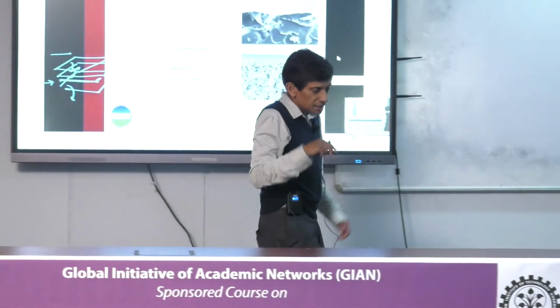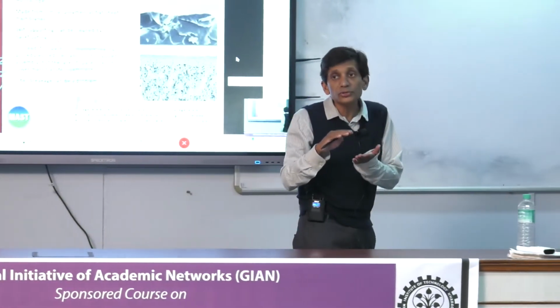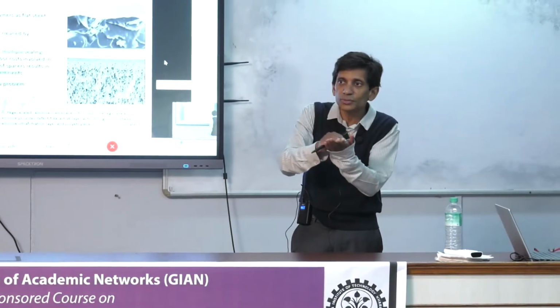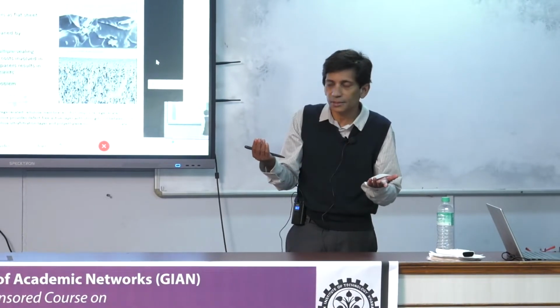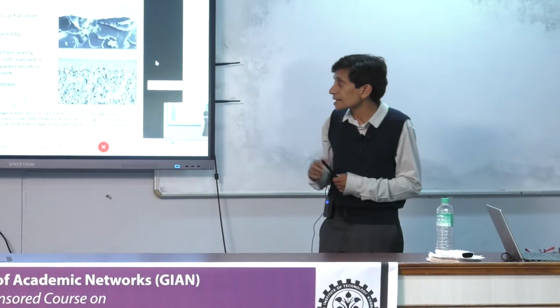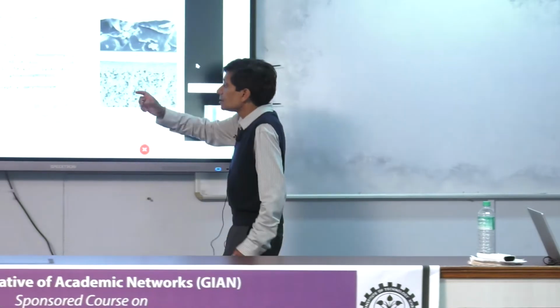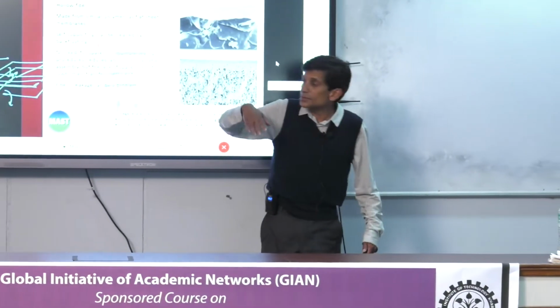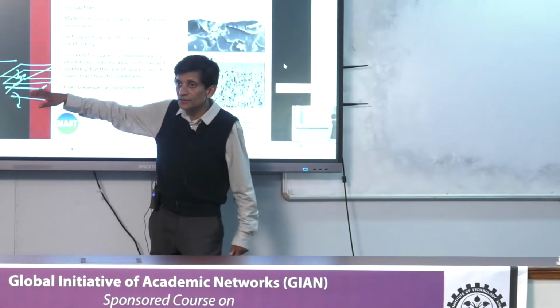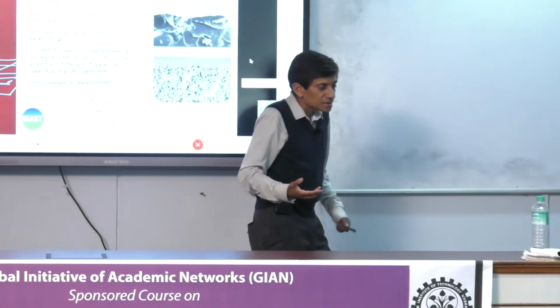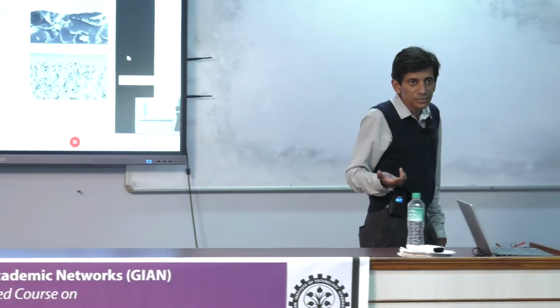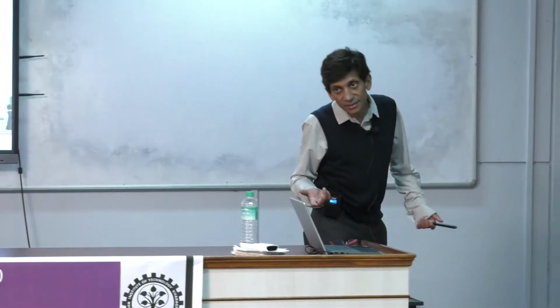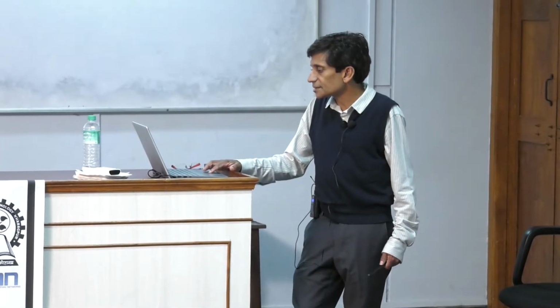In between these feed and permeate channels you must have a spacer, otherwise the two membrane layers will touch and this won't work. The spacer takes up space, and that's why they have a lower packing density than the hollow fibers. But the spacer will also induce mixing in the feed channel, and mixing is a good thing because it breaks up concentration polarization. So there is an advantage also, as I say here, that the lack of a spacer results in lower mass transfer coefficients for hollow fibers.